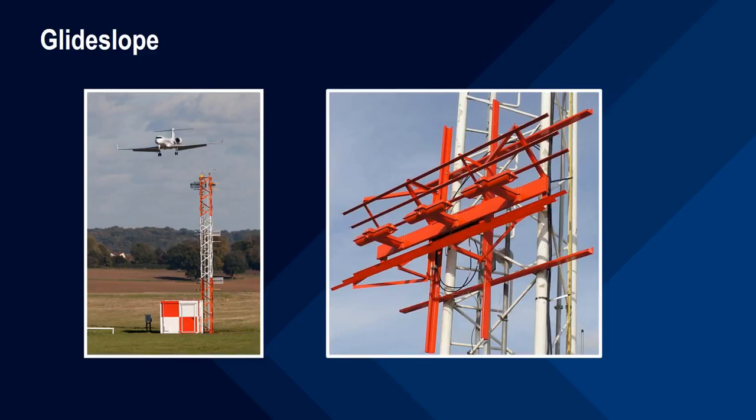Now that we've covered localizer, let's move on to discussing Glideslope. As previously noted, most of the concepts in localizer apply to Glideslope signals as well.